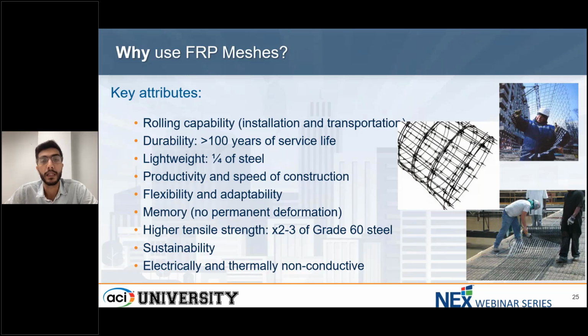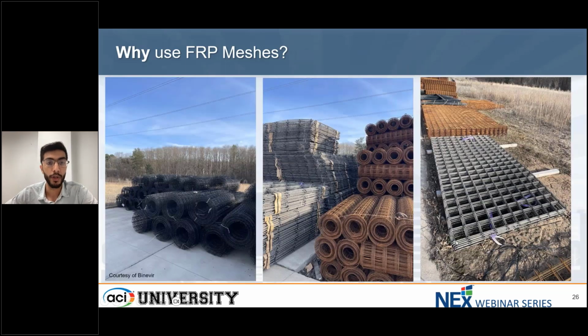When you're using conventional steel, like a steel welded wire mesh, you can easily deform the material during the casting, because the workers are going to work there. They want to cast the concrete. They do not see what's going on under the concrete. They may step on the mesh and they will deform it. So the use of FRP can reduce those kinds of deformation, and that's another specific feature of this material.